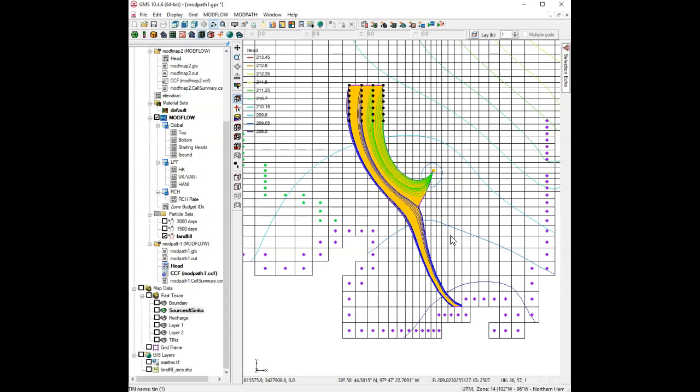It's an algorithm it uses to determine capture zones, and generally that number should be between 0.9 and 0.98. The default is 0.98. But if you have big concave regions like that, you might want to make it a little smaller. Of course, you can always draw your own capture zones by hand using polygons in the map module, but this is an automated way to do it.